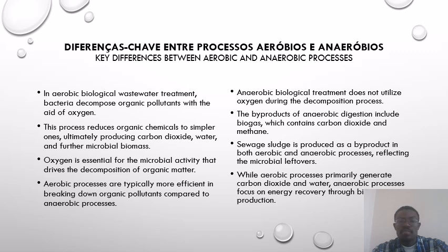Anaerobic biological treatment does not utilize oxygen during the decomposition process. The byproducts of anaerobic digestion include biogas, which contains carbon dioxide and methane. Sewage sludge is produced as a byproduct in both aerobic and anaerobic processes, reflecting the microbial leftovers. Now, while aerobic processes primarily generate carbon dioxide and water, anaerobic processes focus on energy recovery through biogas production.